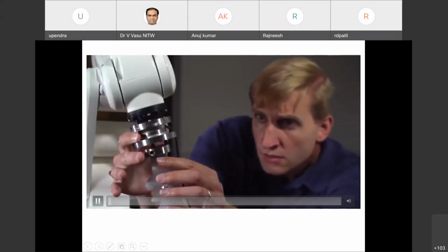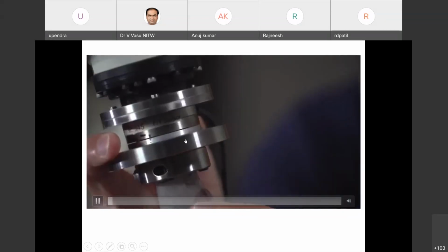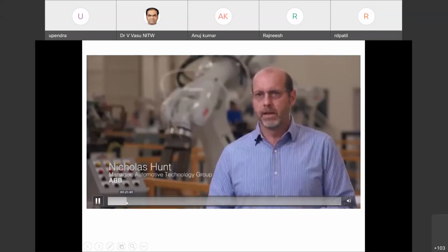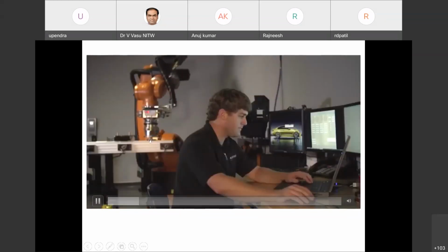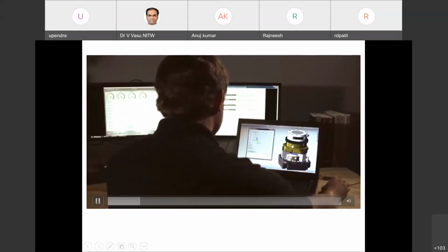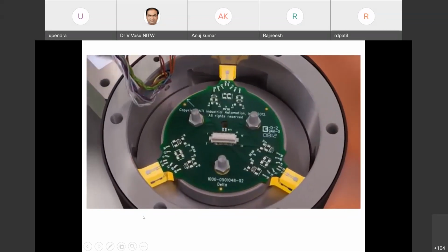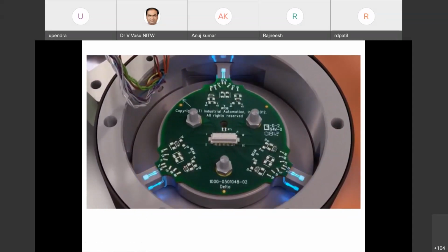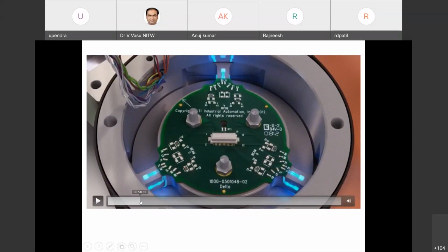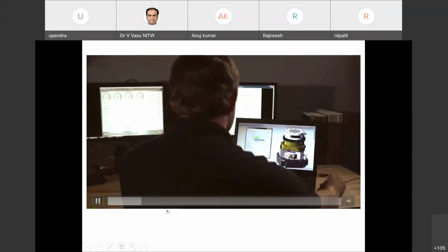So at the end effector, we are going to have reliable, repeatable strain gauge data, which is used simultaneously in all six axes: force XYZ and torque XYZ. You can see the inner components, spokes or beams connecting them. Each beam has four silicon strain gauges that function in pairs to form half bridges.